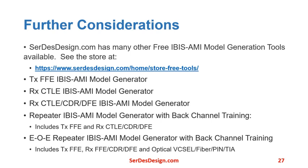It includes the Transmit FFE generator and the receiver with CTLE, CDR, and DFE. There's also an electrical repeater IBIS-AMI model generator that includes back channel training. It includes an FFE generator and an RX FFE with CDR and DFE generator and an optical VCSEL fiber pin TIA generator.